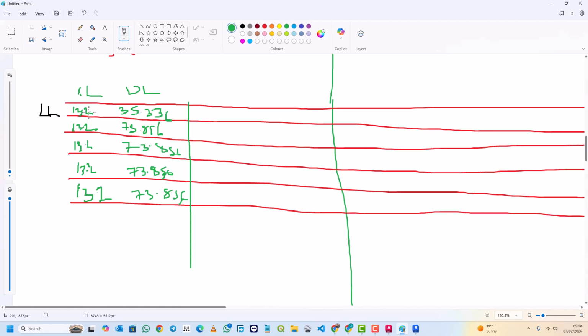Before we accumulate these loads, I'll start with the loads that we are going to use for foundation design. Remember, for foundation design, we just use unfactored load. We call them service loads. So we have to just add these two as they are like this. So we just have to add. Please take note of what I'm saying.